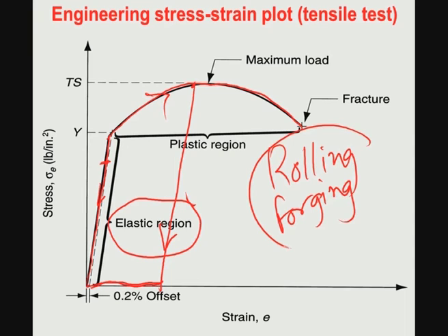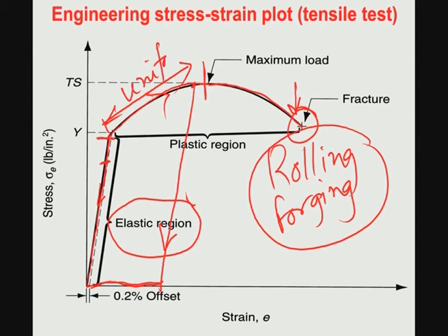So, the larger the strain, the more the material can undergo deformation without fracture. So, you have to avoid the fracture. Another thing, if you get into more details of these deformation processes, this is the region called uniform deformation. Uniform deformation essentially extends from the point of the yield. Yield means now metal will not undergo elastic deformation anymore, metal will undergo now plastic deformation. So, from the point of yield to the point of maximum strength, that is called UTS, ultimate tensile strength.